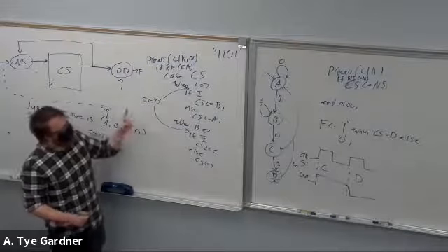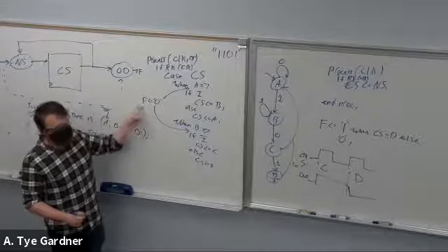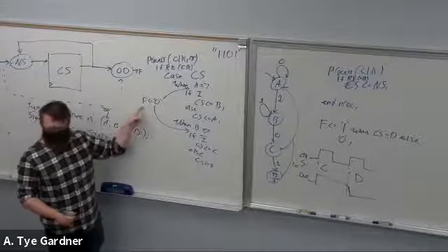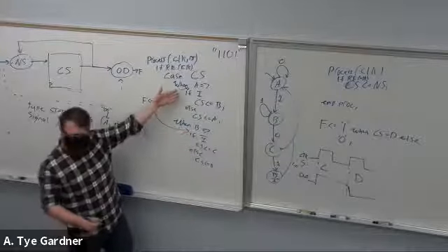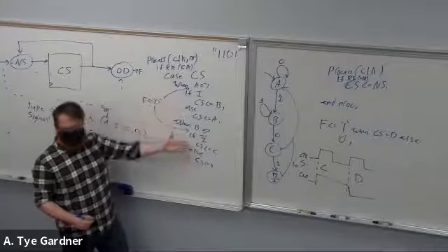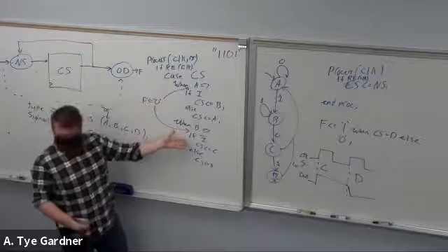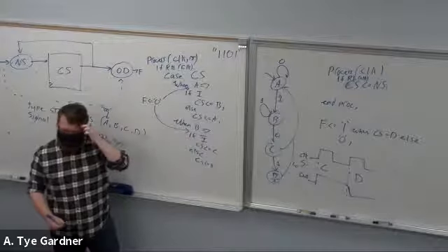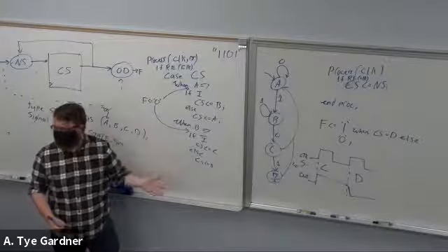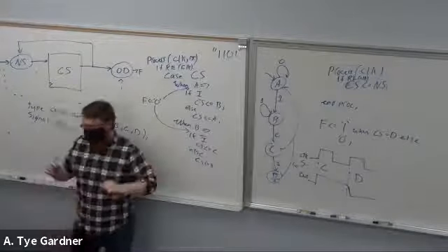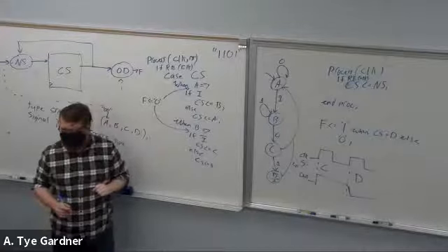Now you have to be careful that you enumerate this output for all states. Don't leave 0 here and then assume that because I was in A and I have to be in A before I go to B, right? Well, if I was in A, it was 0, and I come to B, I would assume that it's still 0. But the trick is that technically it's don't care. It will probably work until it doesn't, which is, again, really frustrating. So if you do this, just make sure that you list all of your outputs in all of the cases.